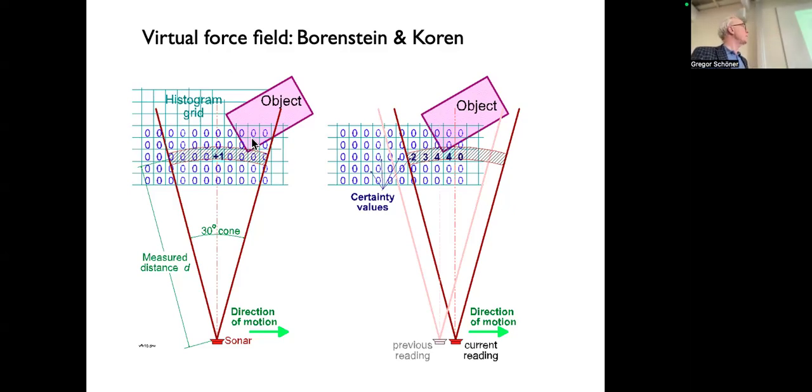And the idea is that you build a grid of the world. As you move, you have to update your position in the grid. It's sort of like mapping. You have to know that now the entries from this particular sonar go into a new cell on the grid. Every time you get an echo, the echo tells you, by time of flight, how far that is from your current position in the right direction. And every time you get an echo, you add a number to that grid cell that increases the probability that there is something there.